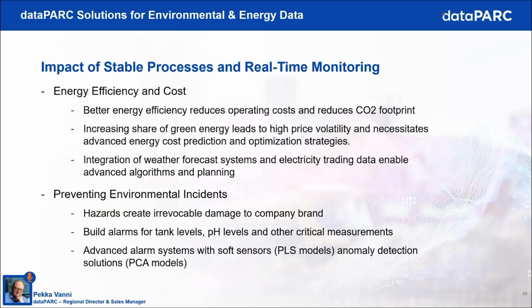Also, to have early warning, you may want to build soft sensors to have an indication of increasing load, like on the effluent treatment plant. And as discussed earlier, some key performance indicators cannot be measured online, but you can perhaps use COD online measurement to estimate biological oxygen demand, but you can also use statistical models to observe obvious changes in process conditions. Next, Molly will present you a use case as an example of our capabilities.